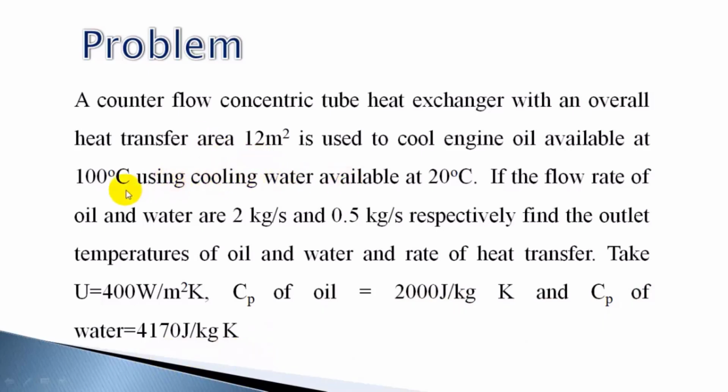Now you are given the inlet temperature of oil. So the purpose is to cool engine oil which is coming into the heat exchanger at 100 degrees centigrade using cooling water which is entering at 20 degrees centigrade. So both inlet temperatures of hot and cold fluid are known, but both outlet temperatures are not known.